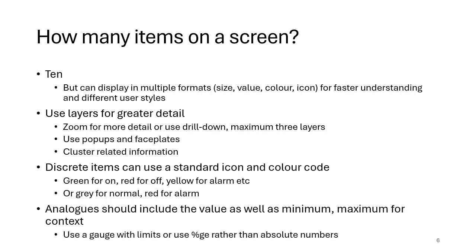And then again, limits. So you might have green for the needle in position is okay, and then you might have yellow limits for alarm, and then red for critical alarm. But again, too many colors can be confusing as well, so maybe you'd go with more muted colors like green and blue. Again, not so important what the colors are. You want to avoid too many colors, you want to avoid too much confusion, but you do need agreement.